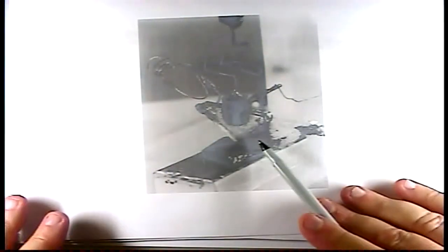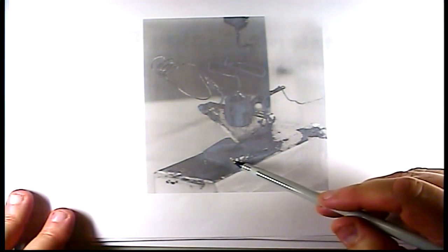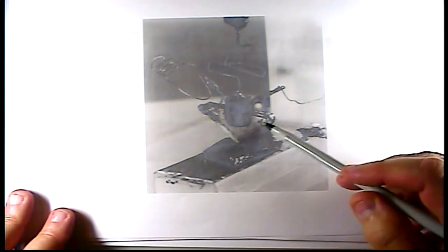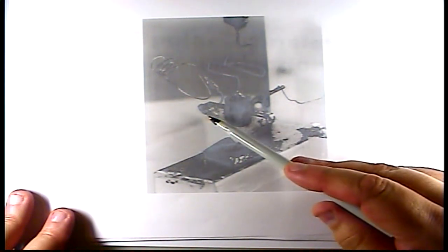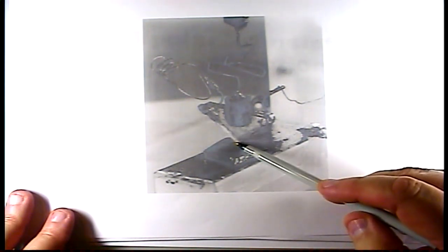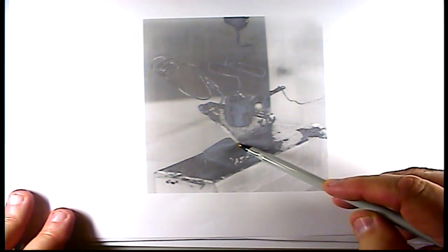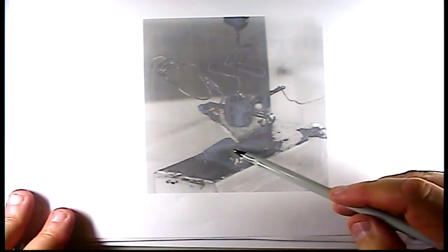But this is a picture of the first point contact transistor. And what we have here is a piece of copper, and then sitting on the top of the copper is a piece of germanium right here. And then there's a triangle of plastic right here. And then right down on this side is a piece of gold leaf, and on this side here is a piece of gold leaf. And down here at the very bottom of the transistor, the gold leaf has been scrubbed off in a very thin line, and that's sitting on top of the germanium.